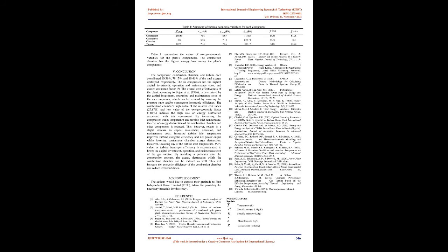Figure 11 is a representation of the contributions of each system component to overall exergy destruction. The combustion chamber with 79.21% has the highest rate of exergy destruction. This was attributed to the chemical reaction as well as the large temperature difference between the burners and the working fluid. Oyedepo et al. 2015.